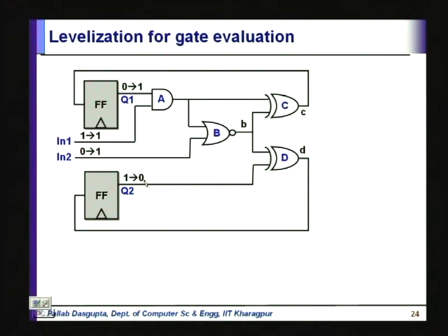In an event driven simulator, what would we have done? We would only look at the ones which have changed and then schedule output events there. Now, see, if you follow that kind of principle, what might happen is that you may first schedule the gate A that causes a change in input here, because this input of A was 1, it remains at 1, this was 0.